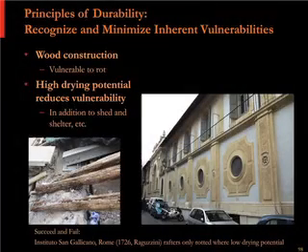And then they did a really smart thing, and this is typical on a lot of Renaissance and Baroque buildings. The way they set the brick on a loggia or a courtyard or some sort of ledge or band course was they would chamfer cut the underside, like you see in this little sketch in the center, so they can get the joints really, really tight. Because the mortar is a lot more absorptive than the brick. So what they're really doing is minimizing the area of the mortar because it's so absorptive and maximizing the area of the brick.